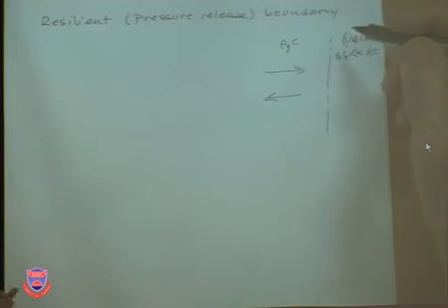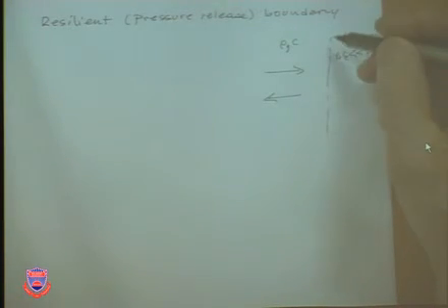In automobiles, for example, they're modeling the interior of a car. Okay, we have all these very nice, fancy software systems, but boundary conditions are always the most difficult part. We do not know. They're always empirical. We try various values and numbers. So that's why it is important to have a good feeling, good understanding of what boundary conditions are. In this case, we covered one extreme case, perfectly rigid. There's no such thing, of course, perfectly rigid. And this is the opposite, perfectly resilient, meaning pressure release.